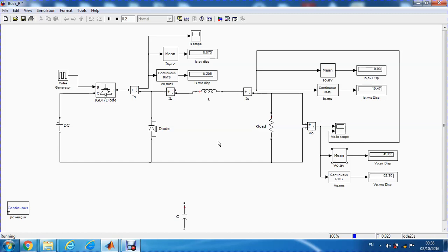So what does that tell me actually? It tells me that I don't need to get a big value of inductor. It's very, very hard to get that big value of inductor. Whereas what I can do is design a controller circuit, like I can use Arduino, PIC microcontrollers or any other digital devices to generate such a high digital frequency up to 20-25 kilohertz, and then I can achieve a very good result with that.